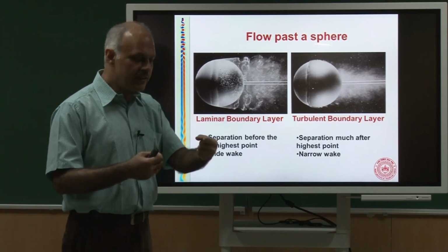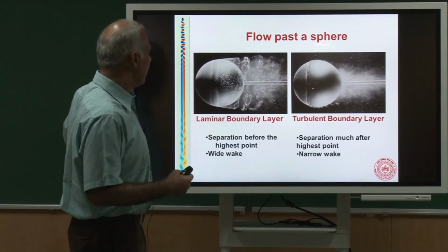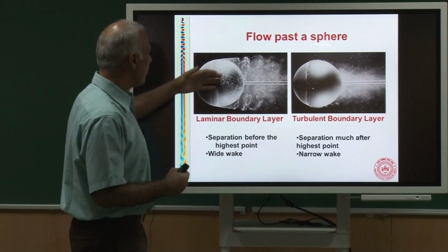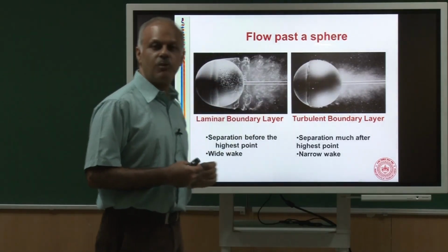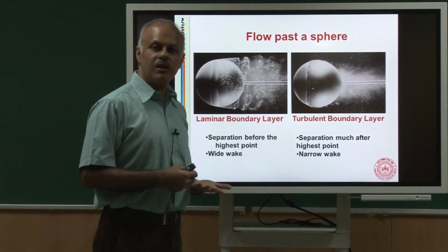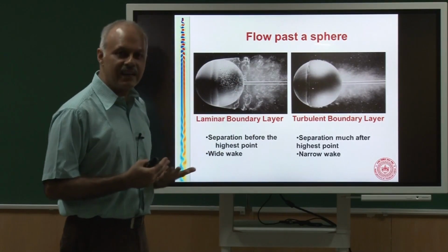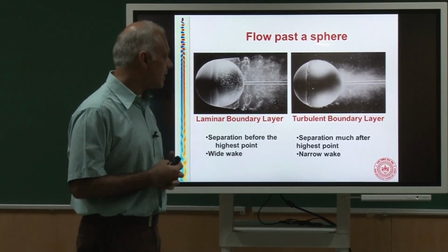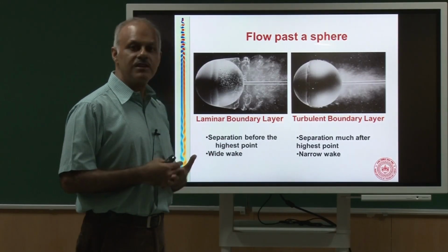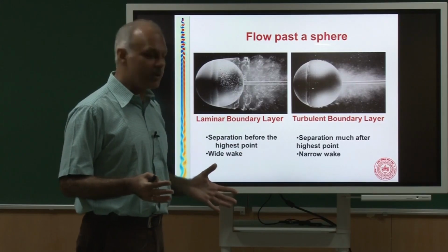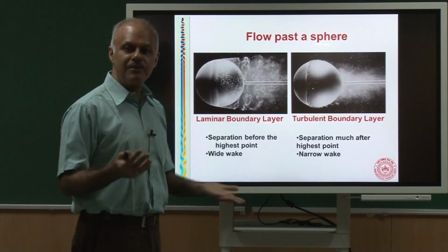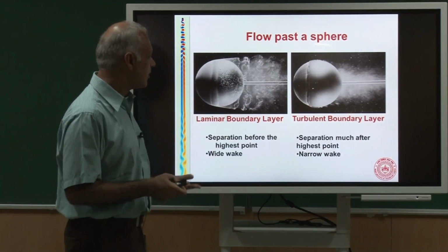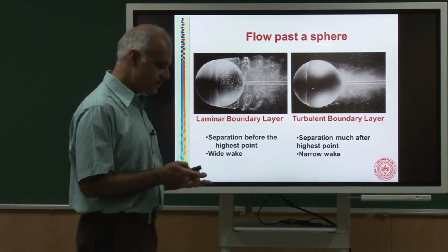So if I pull this body, I am transferring energy from the body to the flow outside. It is larger here and the transfer is smaller here, and therefore it has smaller drag. In fact, when I design a car, a sports car or a sedan, I would like to disturb the flow as little as possible, because if I energize the flow outside the car, it must be coming from somewhere, and it eventually comes from the fuel that I burn inside the car.